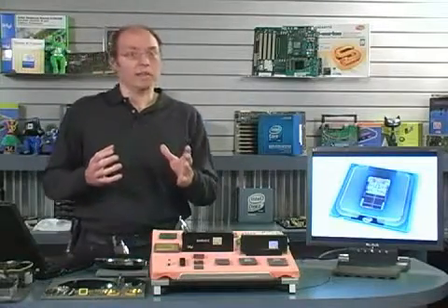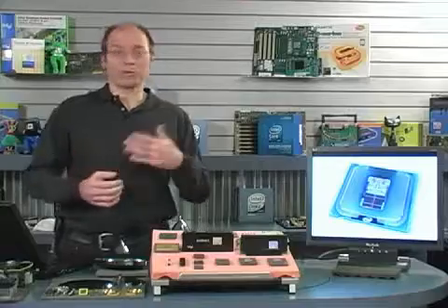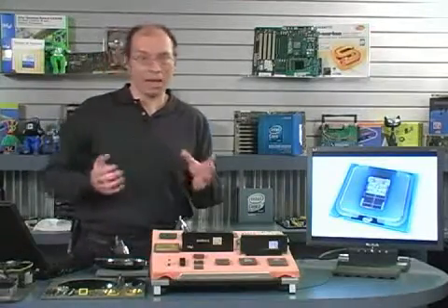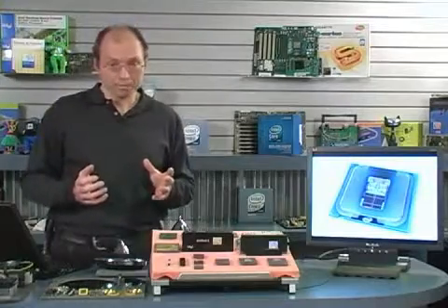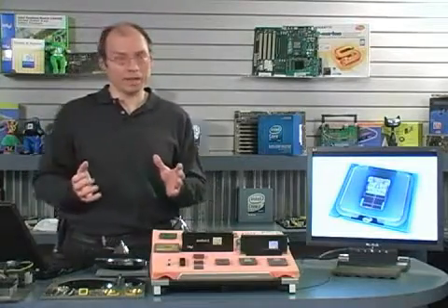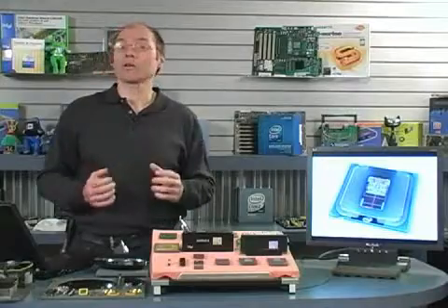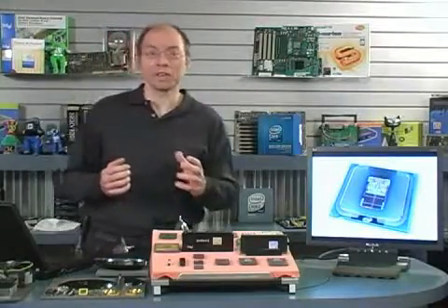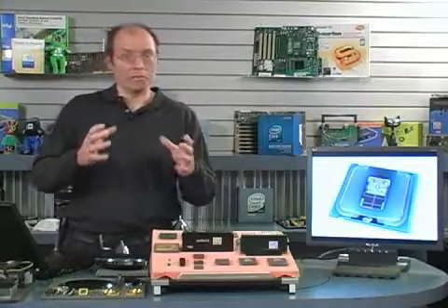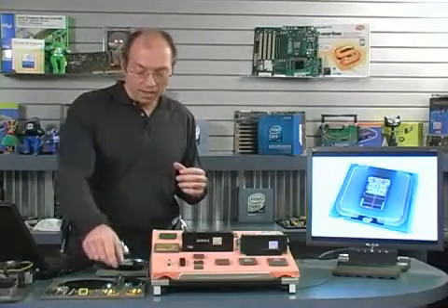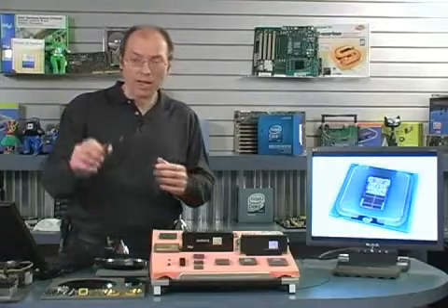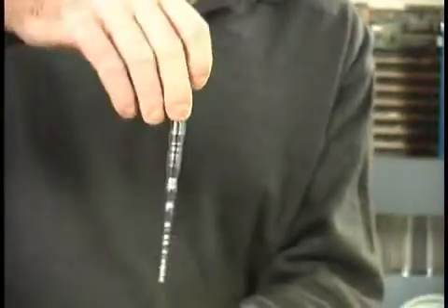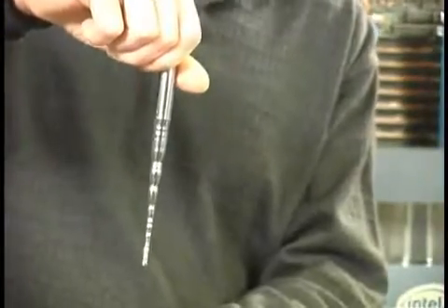So what happens is we take the sand, melt it down, and put it through a purification process until we extract the 99.999% pure silicon. Now, even that's still not ready to make chips out of. We need the silicon not only to be pure, but to be in the form of a crystal. So the pure silicon is melted in a vat, and a seed crystal, like the one I have here, is dunked into the vat of molten material. It's slowly turned and then pulled out.